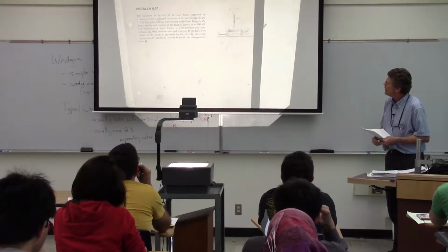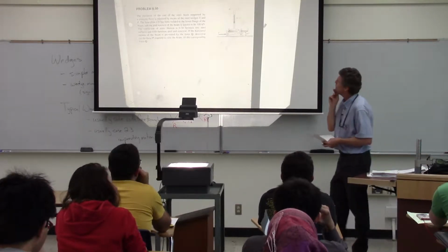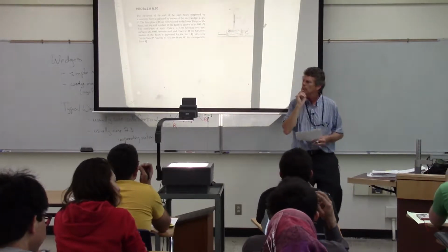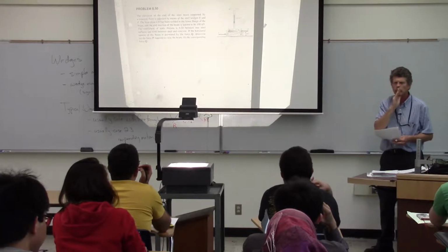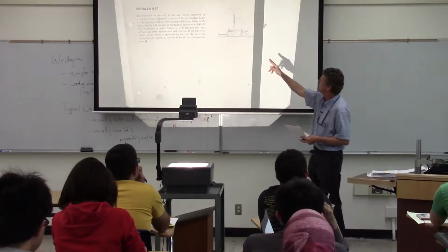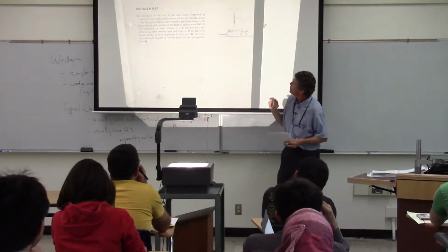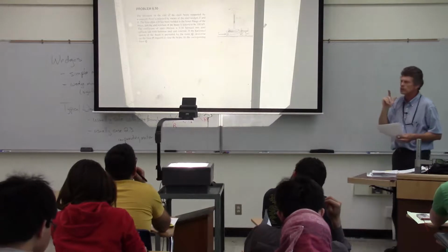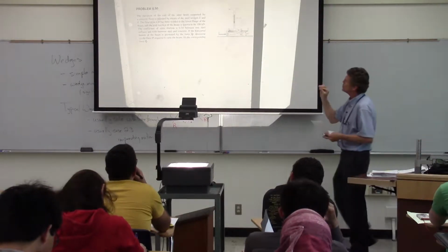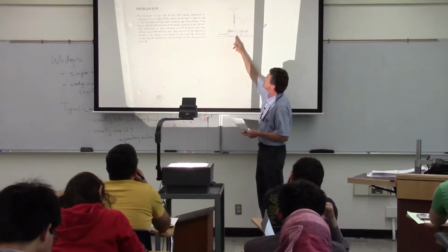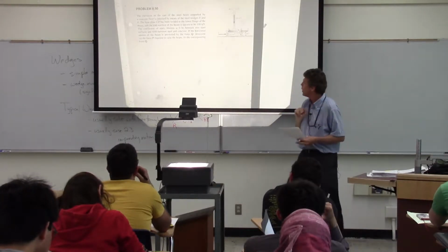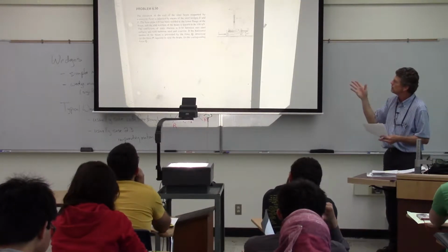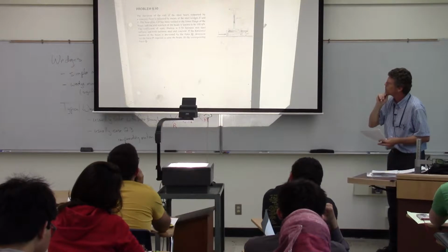And then the other thing we need to think about is that we're overcoming friction from E being pushed in there, but we also have that other wedge F, and we need to think about it too because it's not glued to the ground. It's sitting on the ground with a coefficient of 0.6, and all the surfaces have a coefficient of 0.6. So we also have to check when we calculate that force, will that wedge F move out? So we're going to have to check that to make sure that if we put enough force to get that thing to lift, will F go charging off?